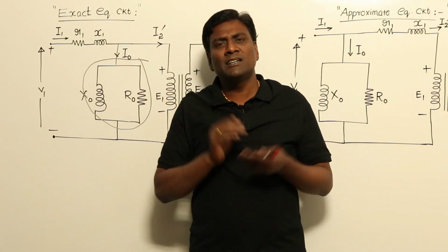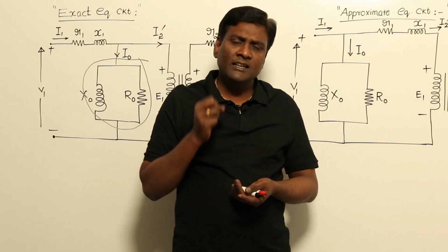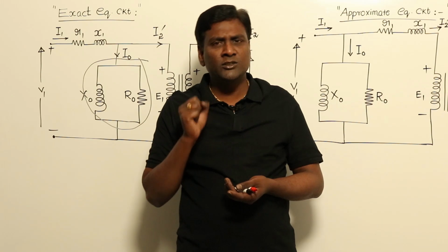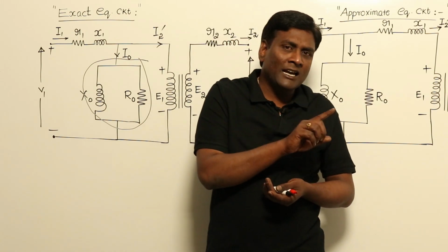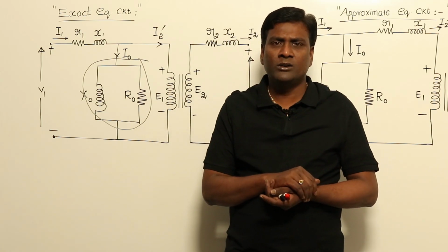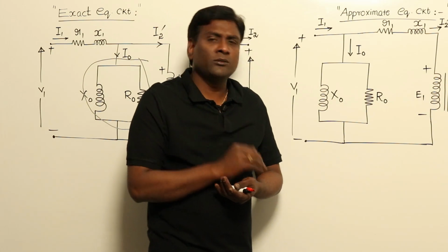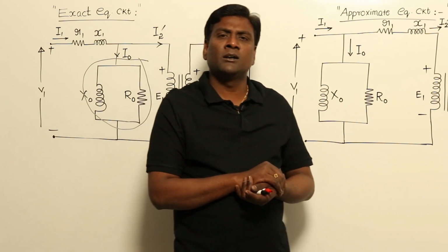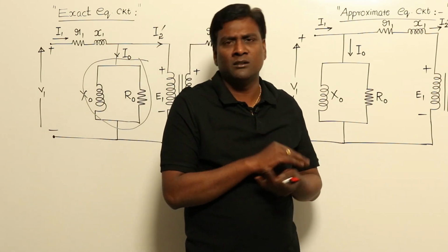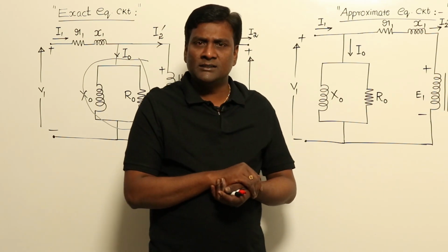Now normally an inductance, will it absorb any power? Will it absorb any energy? No. It will take the energy, store it, give you back. So leakage has been modeled in the name of inductance, means that it should be lossless only. Now you may ask me, though it is lossless, why you are modeling, or why you are focusing on leakage? Maybe down the line gradually you will understand.